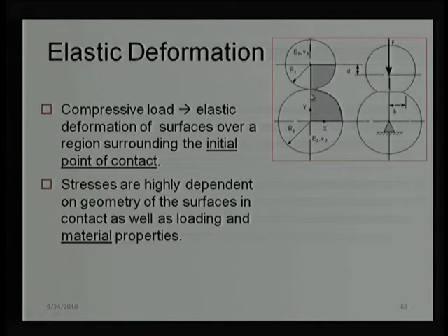So it is not necessarily only solid to solid deformation, but liquid to solid deformation also occurs. However, Hertz was the first person who developed this kind of relation, and he mentioned deformation due to the solids. That is why we are just repeating those things over here. Otherwise, the liquid also can deform the surface, and we need to account for that elastic deformation, which is finally going to generate the elastohydrodynamic lubrication mechanism, which is the most demanded, most optimum lubrication mechanism.